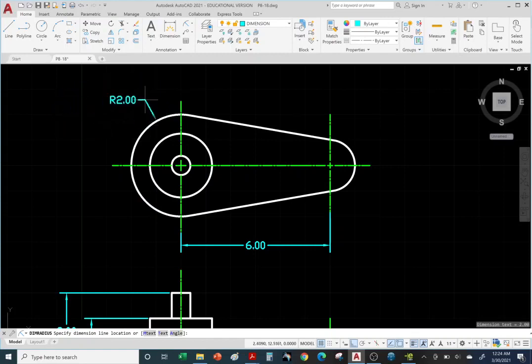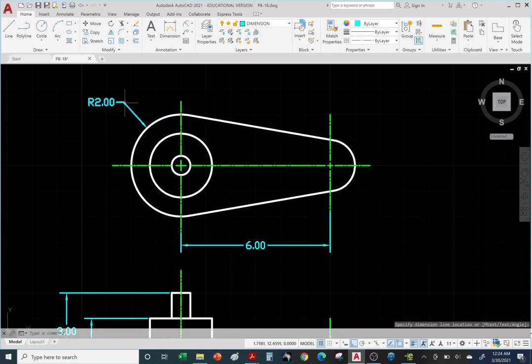One problem you may have as you're locating your radius is you may want to have ortho off and/or object snap. Sometimes it doesn't move where you want it. As you can see, it's moving all over the place. So if you're having issues locating your dimension, you can always turn off ortho or object snap. So let me go ahead and click out here. Later on, if you try to relocate it using the grips, it's not going to cooperate because we have ortho on. It's trying to only move vertically or horizontally. So you can always turn off ortho and see now you have more freedom.